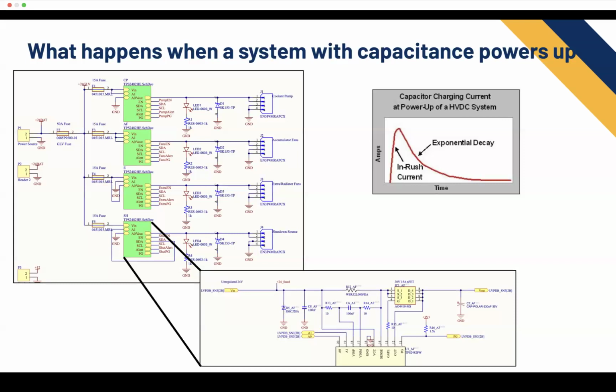It's something to be careful of because you want to make sure that when you power on a board for the first time, if any of these eFuse ICs were broken, you could possibly burn fuses if you pull too much current. That's why it's also a good idea to always set the current limit on your power supplies when you are testing these boards before you plug it into real batteries. Always test with a power supply first, and that way you can actually see how much current the board is pulling. And if it's too much, something might be shorted. But yeah, any questions?